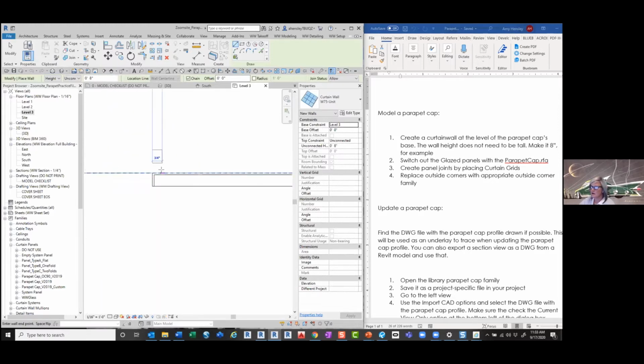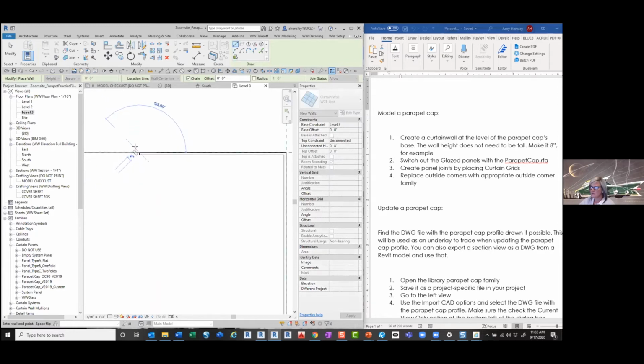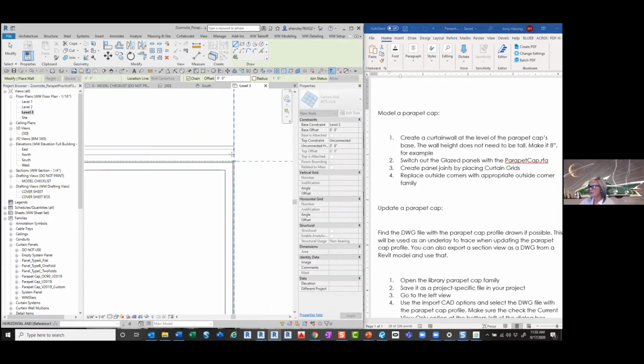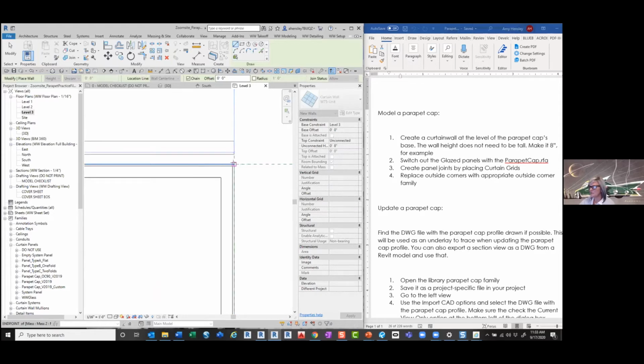And now you can see I've got a wall attached to my mouse. I'm just going to drag it down here, and I can either pick on the corner with my little corner snap. If that reference plane highlights, it means I'm going to land perpendicular on it, and I don't have to be necessarily as careful. If I get up here, it's going to go funny. But if you get close right here, it's basically snapping to that. So I'm going to pick right there.